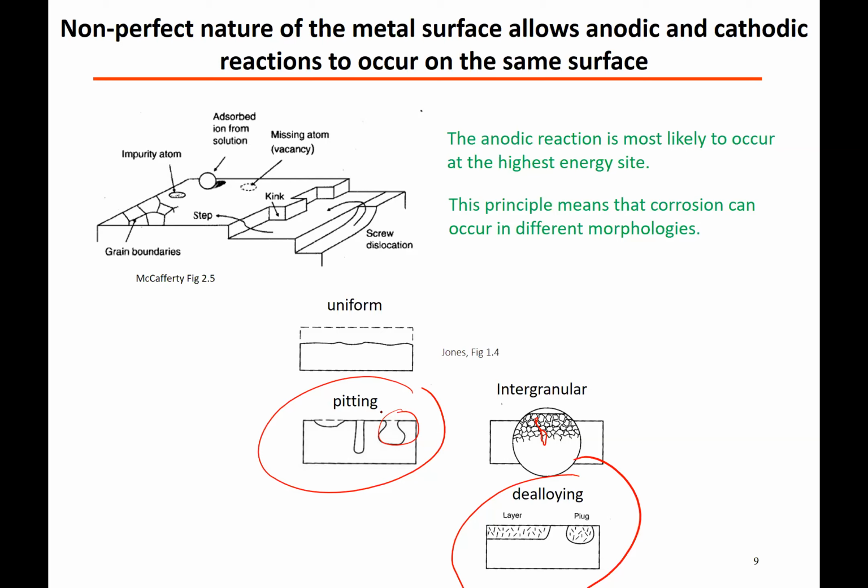One of the examples that I gave was battery electrodes, where you can have two metals, and then you can de-alloy one of them, and what's left behind are these pits. And what you can do is then put in your active material in the pits, and the liquid electrolyte in the battery can actually penetrate those surfaces better and deliver the electrolyte that's needed to make a battery work better.